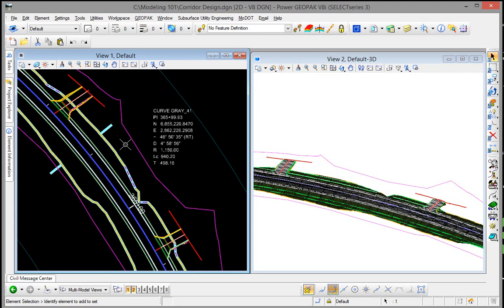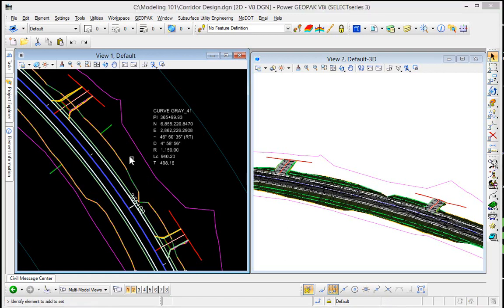Now, what you'll want to do is when you're placing your driveways or your intersections, you'll be given the prompt to select the corridor to clip. You can actually do a reset to cancel selecting the corridor to be clipped and then add them later as I just showed you, and that'll save a lot of time where you're not processing all those clipping references as you're still designing your corridor.